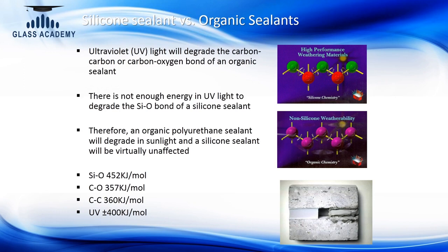So essentially they can be degraded, but they are stabilized by using an external stabilizer which has a limited life. But if you look at silicone, the silicone polymer has an inherently stable backbone. This essentially gives it an inherent stability against exposure to UV in sunlight. This is one of the key differentiators.